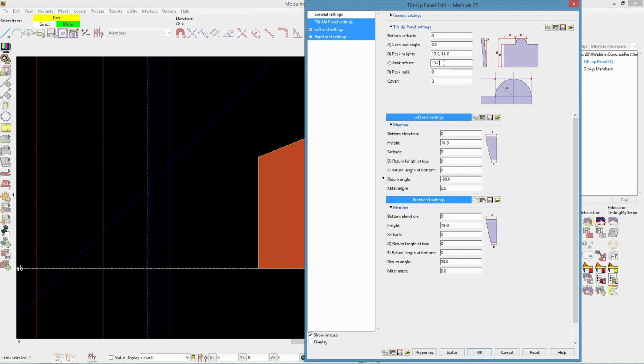To make it go straight up and down, which will show once it's added in here, I'm going to do a comma, and at my 10-foot in, I'm going to go flat 10-foot elevation, 10 foot in, and then also at my 10-foot mark, now I'm going to go up to a 14-foot elevation. I'll add in another 14 foot to make it square up top.